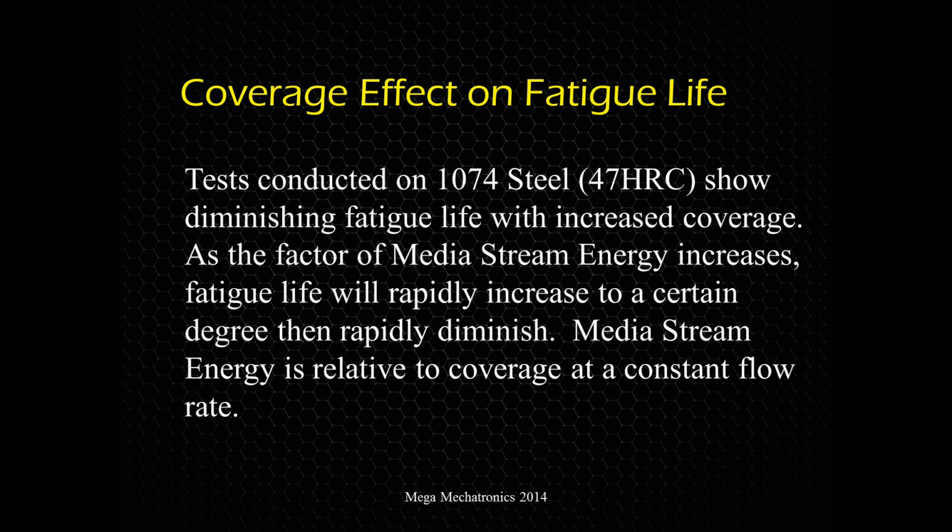As the media stream energy increases, the fatigue life will rapidly increase. Starting with a raw workpiece, you send it in there, and the fatigue life is going to increase with the amount of time it's in the process. Then it peaks, and then it diminishes in fatigue strength almost as fast as you gained it. Media stream energy is related to the coverage at a flow rate, and it's sort of a universal language to compare processes. So think of that as the coverage amount: the more media stream energy, the more coverage.